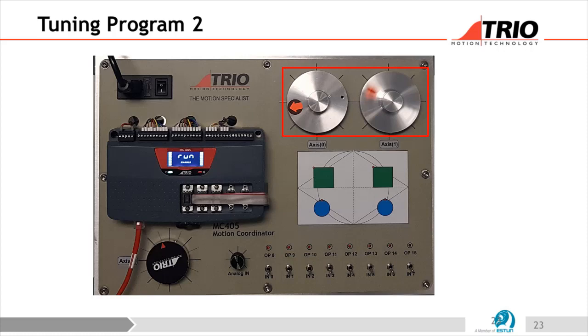Could you run them as like a torque feed forward instead of a speed feed forward? Yeah, we don't really. The thing is, we have no internal value in the Trio that's proportional to torque. We're generating a speed value, but there's nothing proportional to torque, so there's nothing there really to feed forward. And likewise, because they're not speed controlled drives, the velocity feed forward won't work because the output's not proportional to speed.